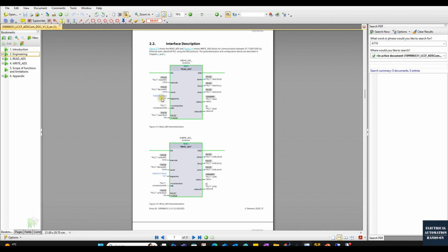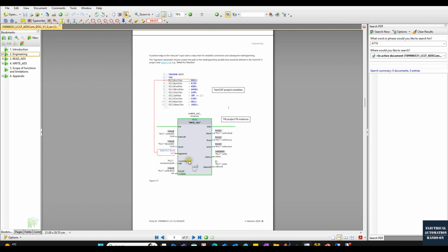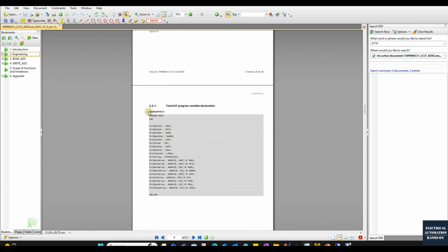As we can see here, this is one variable named instant. This is the bool. But in the real case, if we scroll down here, the Siemens example project can actually communicate with all those variables. Keep in mind, basically this area is a single variable for testing purposes. But this area has bool, byte, word, dword, integer, int, and real.